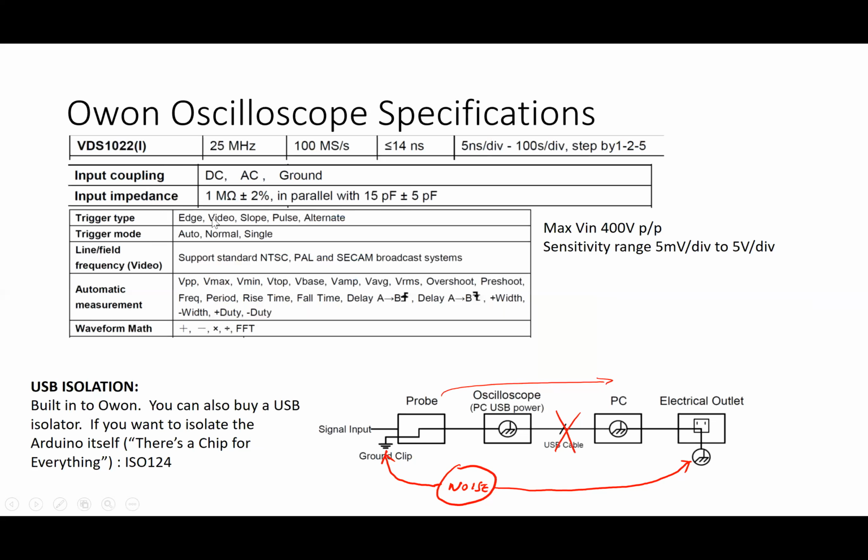Triggering, in the case of the square wave, we'll trigger from one edge, and you'll see we can trigger from a rising or a falling edge. There are other options here which you can explore as needed. Usually one will leave it in the automatic or normal triggering modes. Single triggering is when you want to look at an event that is not time repeating, but is triggered by some other source. So you can use an input to that multi-purpose pin to trigger the trace and then see what happens. In fact, you can even see what happens before it's triggered, because this digital scope collects signal all the time, and there is a way of setting this up so you can see the signal prior to the